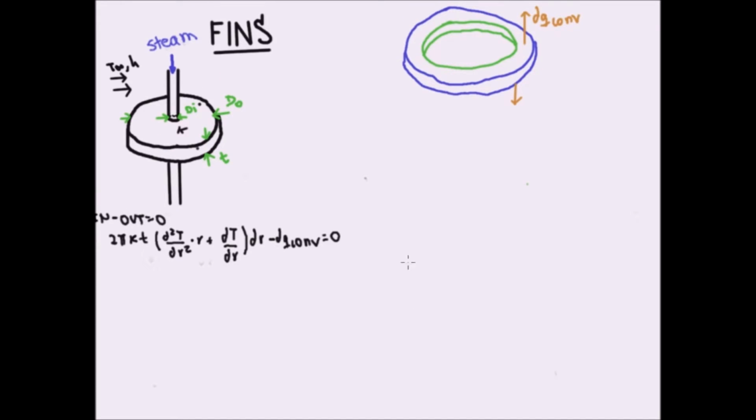Okay, now we will move over to the convection term. We must note that the convection occurs between two media. In this case, it's the surrounding air and the thin material. As opposed to conduction, convection also includes the advection heat transfer, that is due to the bulk velocity of the fluid. Conduction only depends on the diffusion within the material, and convection actually is the combination of the diffusion within the material. In this case, it would be the diffusion of the air at the boundary layer right on top of this surface, and the advection heat rate that depends on the bulk velocity of the air. However, I will go into more depth when we reach the convection part of the course.